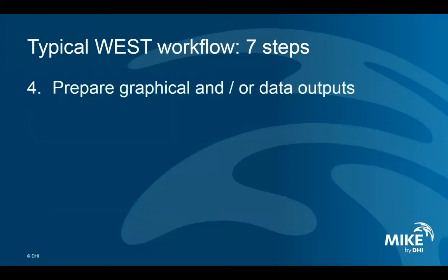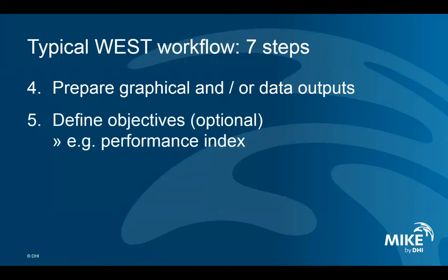Fourth step, I'm going to create some graphical outputs like plots and tables, to view the simulation results dynamically as the simulation progresses. Fifth step, I would consider it optional. I could create some objectives, cost functions in other words, like a performance index, for instance, which could combine effluent quality indicators, energy consumption indicators, and so on.